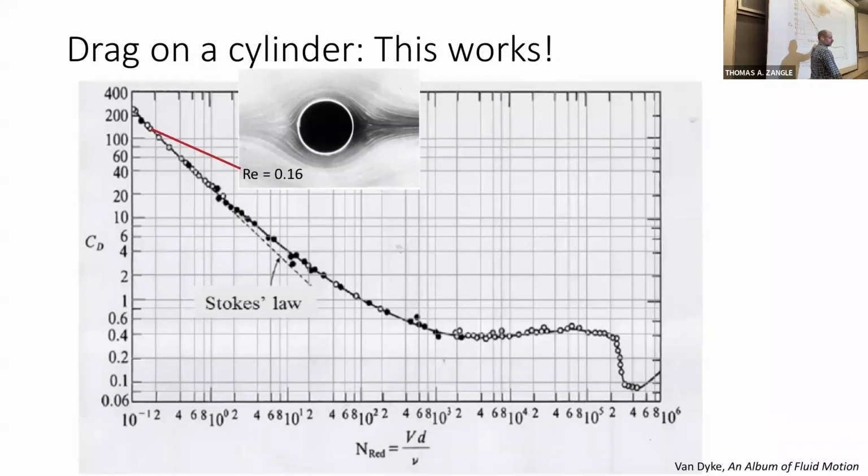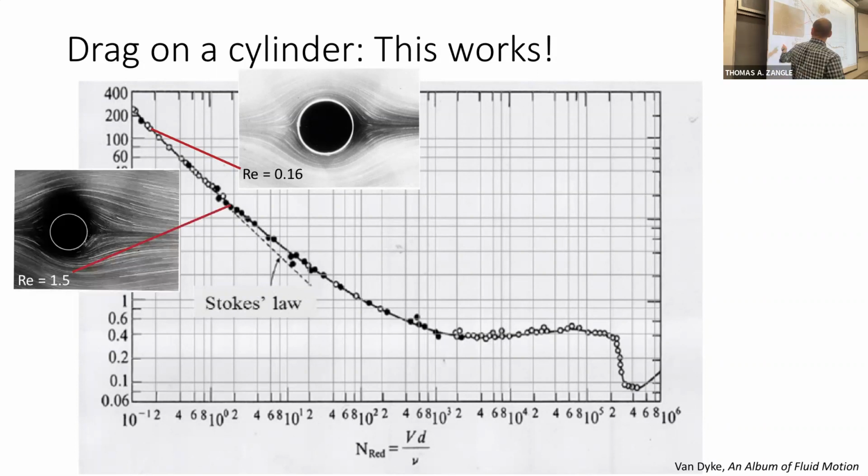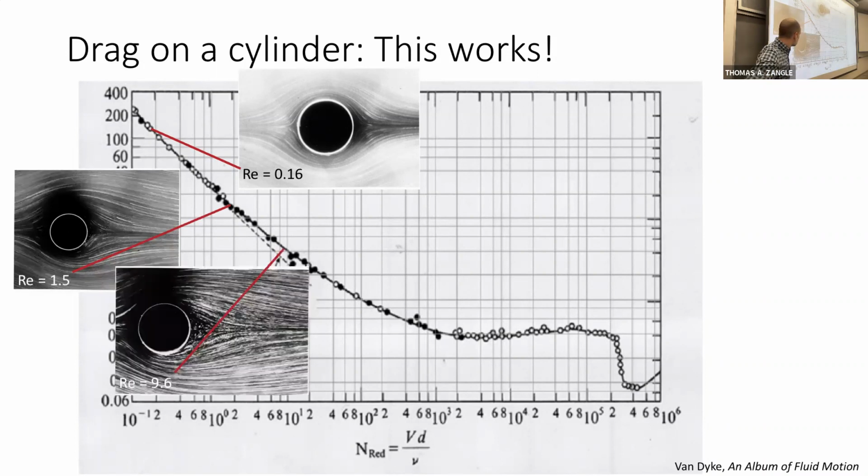So it tells us something really fundamental about everything from, so this is what flow at really low Reynolds number around the cylinder looks like. We see it's symmetric on the front and back side. This we would describe as creeping flow, like ultralaminar flow. We'll see some examples and videos of this as we move through the class. This kind of flow is on the line. As we increase Reynolds number, we have something that looks still pretty similar. We increase Reynolds number again, we start to see some asymmetry front and back. There's actually a small wake forming behind this, but again, it's on the line.